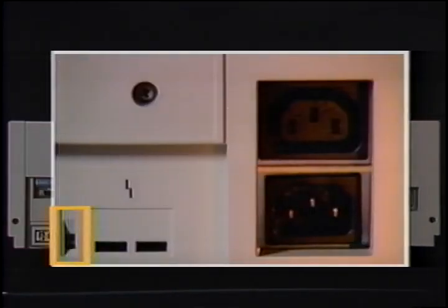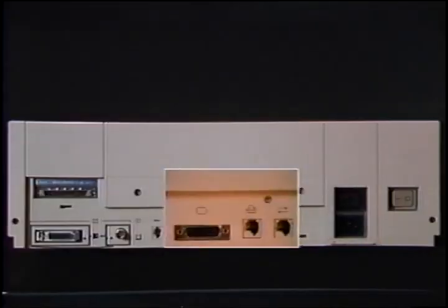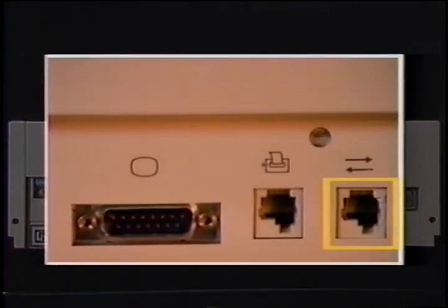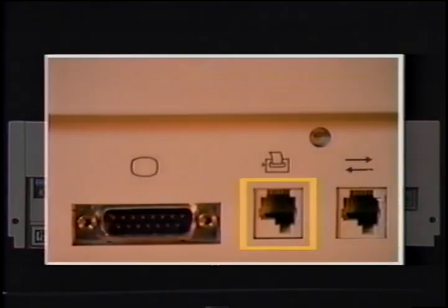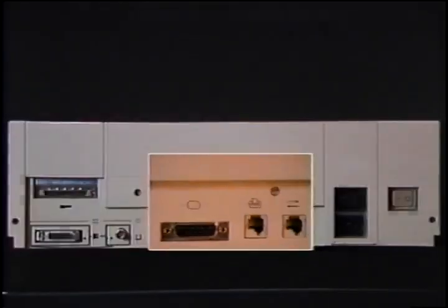A data terminal enabled switch on the Model 40, when up, allows a console video terminal to be used from the printer's serial line port. Asynchronous serial ports are used for a call-out-only communications line, system printer, video connection, mouse or tablet, and keyboard. The halt switch puts the system into console mode for communication with the firmware.